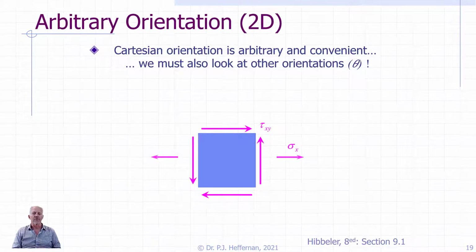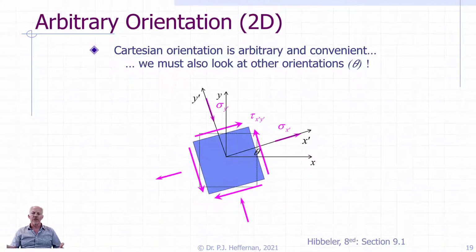and our shear stresses resulting from it. But now we need to make sure that we consider all our other alternative orientations in order to get our maximum normal and maximum shear stresses. And so here we have the XY axes. And as we start to flip around our differential element and change our angle theta, shown here, we're going to come up with different normal stresses.